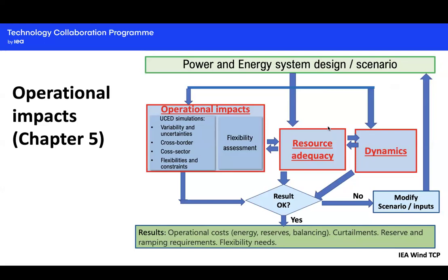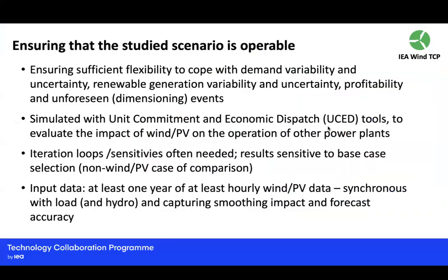Then there are some recommendations for the operational impacts, the unit commitment simulations. This is to ensure that the studied scenario is operable, hour to hour, or 15-minute to 15-minute, or 5-minute to 5-minute, whatever is how your power system is operated. You do it with these unit commitment and economic dispatch tools.